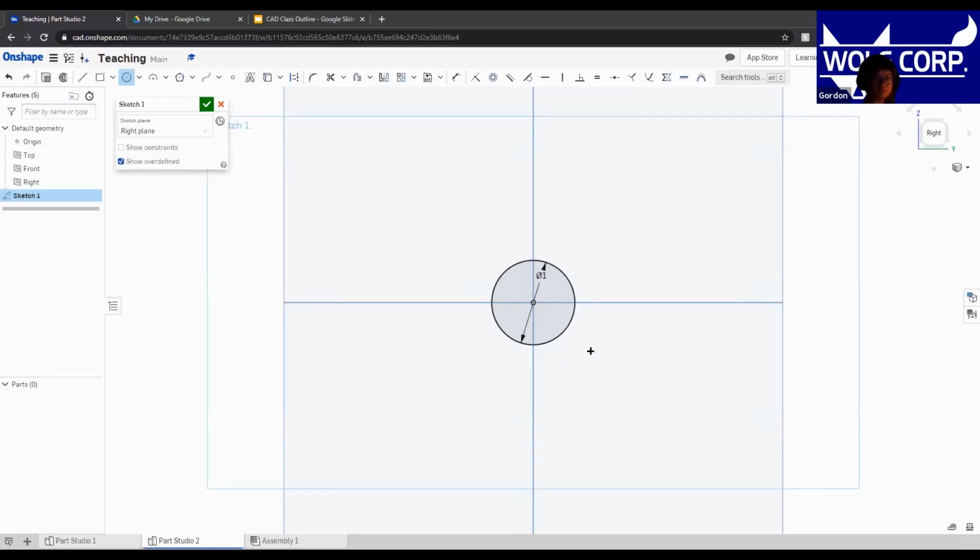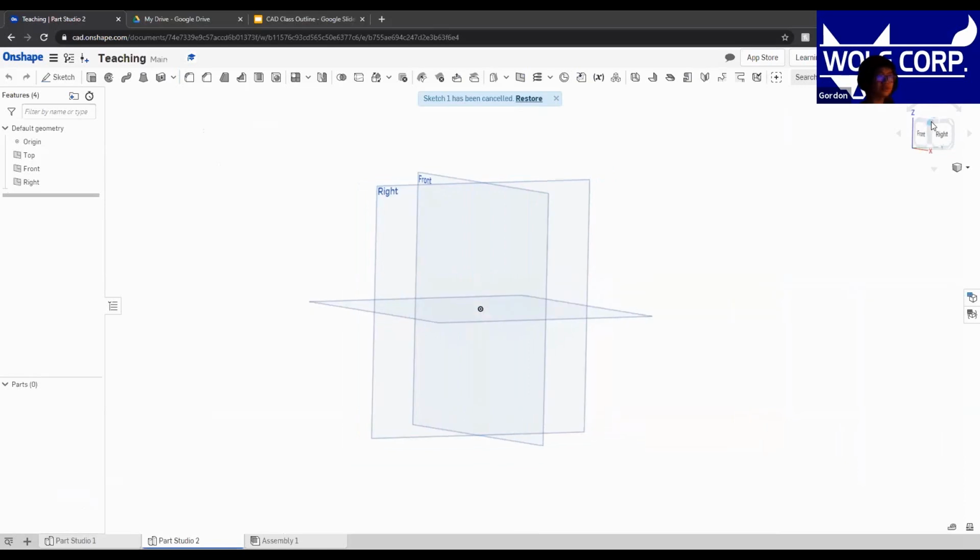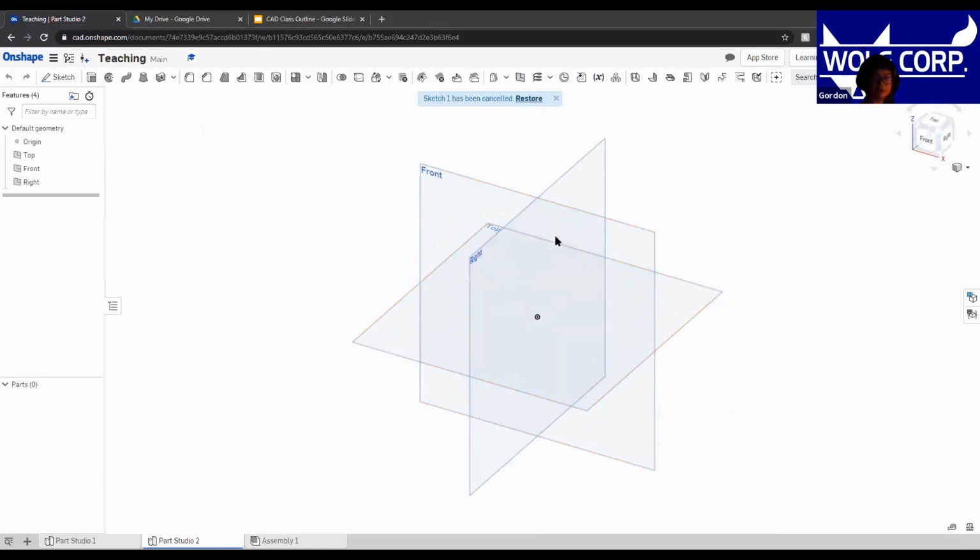Wait, how did you get to the empty thing? All right, so in order to do that, I press this bottom left plus sign to create a new part, and then I press Create Part Studio. Not assembly, but a part studio. I clicked it, and then I have a new field. It should be up to here.